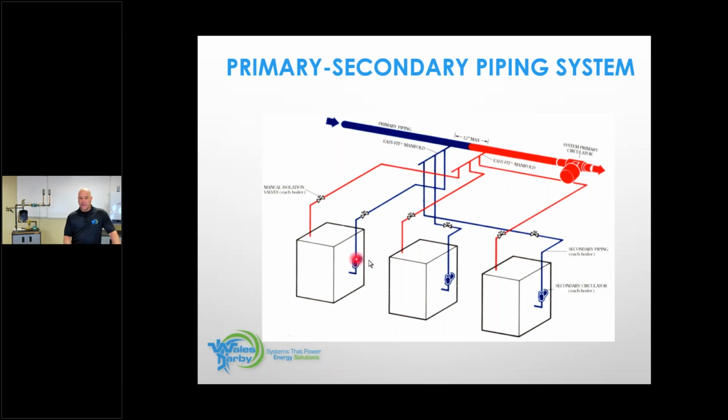If I did this boiler here as the first in and first out, it would do the majority of the work, because these other boilers would see preheated water going back to them, so they would not run as hard, maybe modulate, if it's modulating equipment, at different rates. And your number one boiler, let's say it's cast iron, would see the greatest delta T. So we just do a reverse return on the 3 boilers going in and the 3 boilers going out for supplies and returns. That's a form of primary, secondary with multiple boilers.